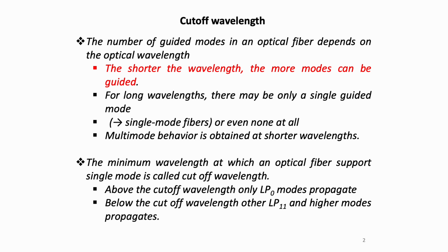Today we are going to see a very important parameter in optical fiber communication. That parameter is the wavelength, or the frequency. Based on that, we can calculate the number of modes guided by the optical fiber. If the wavelength is shorter, it can guide more modes. Vice versa, for a longer wavelength, only a single mode is guided.